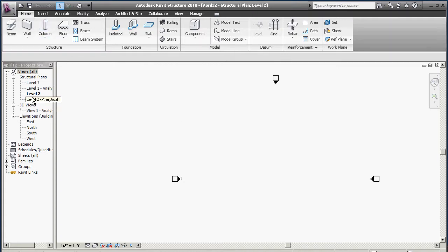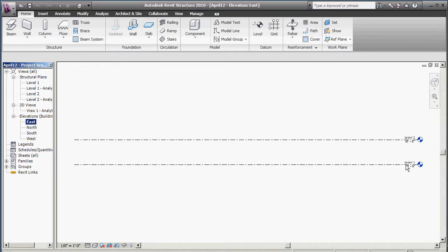So once you're here, of course, remember that we do everything thinking about levels. We're going to start perhaps by just going ahead and changing the level here, 1, 2. We're going to make the assumption that we're going to have at least a third level and a level down below here, but we're going to tie them to the level above.